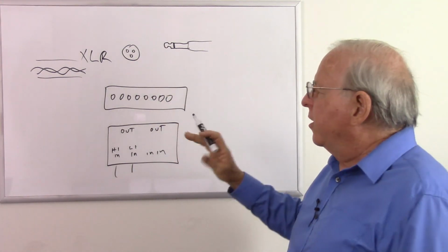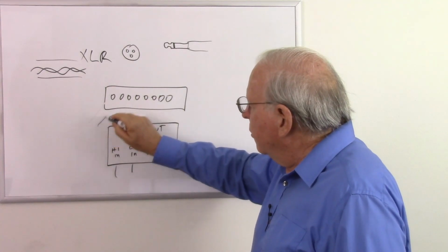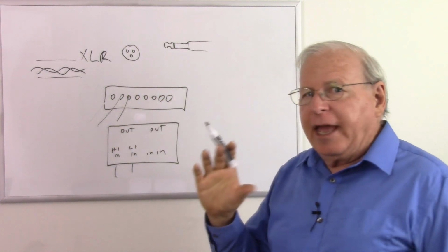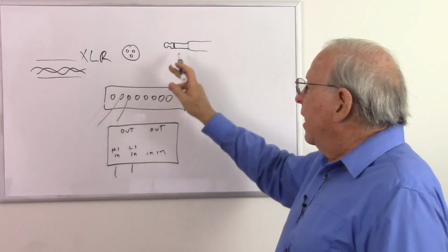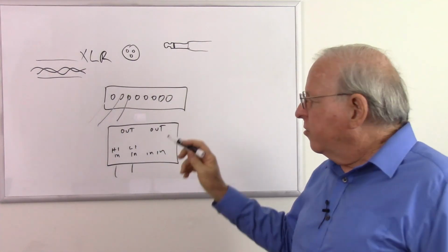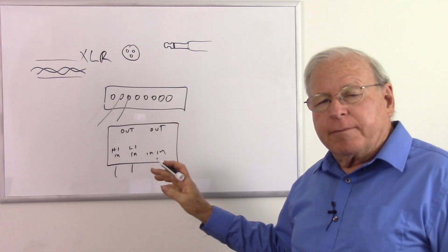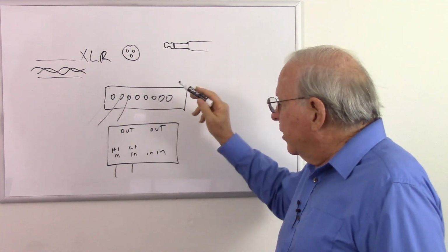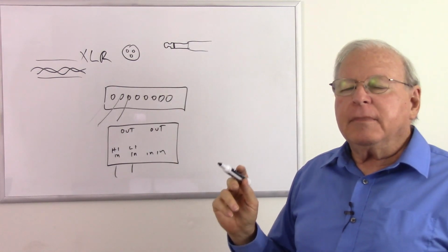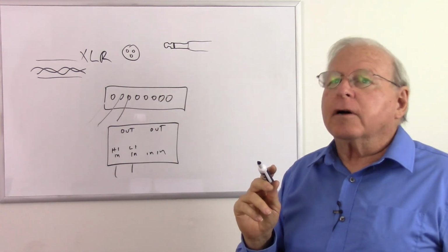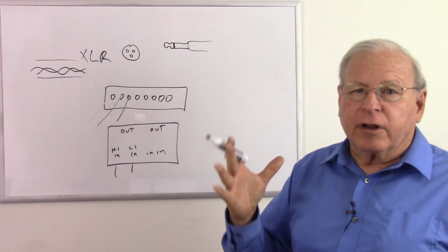So typically what you're going to do is have microphones go directly into your mixer, and if you have instruments which are going to have the phone plugs instead of the XLRs, those are probably going to go into a direct box so that you can match them to your mixer. And also you may have speakers that some are powered and some aren't.